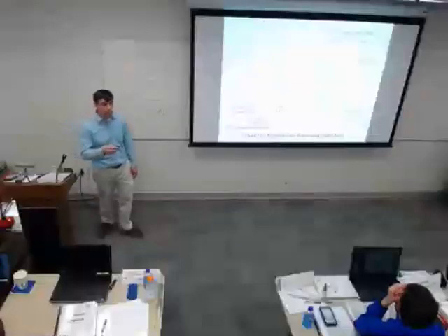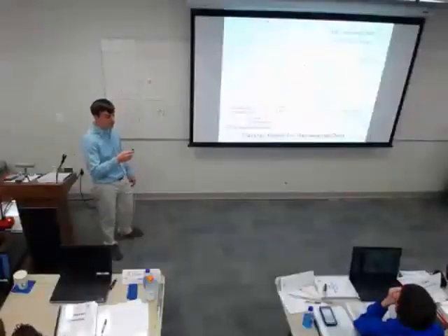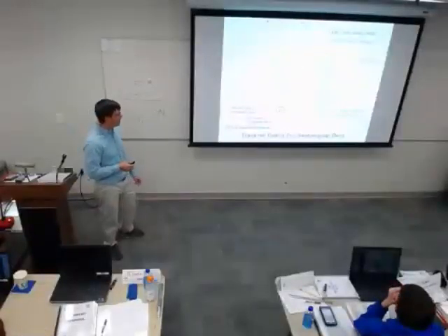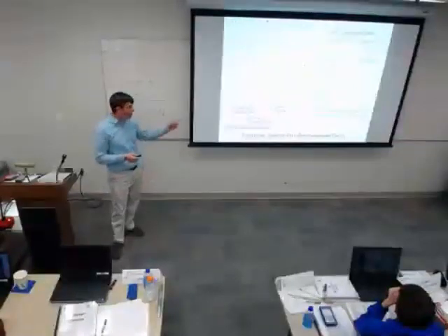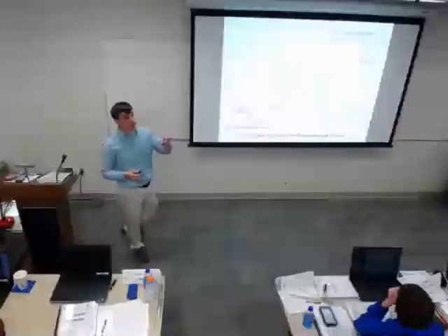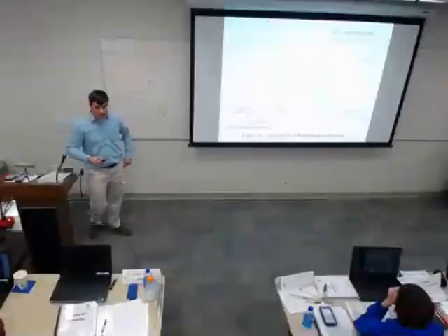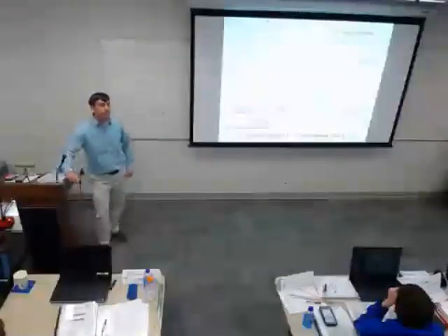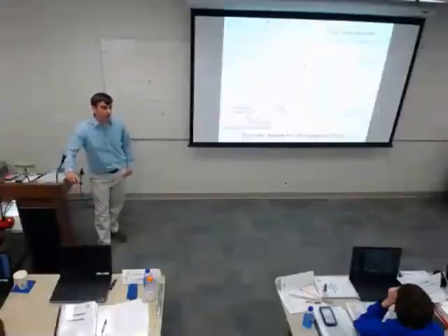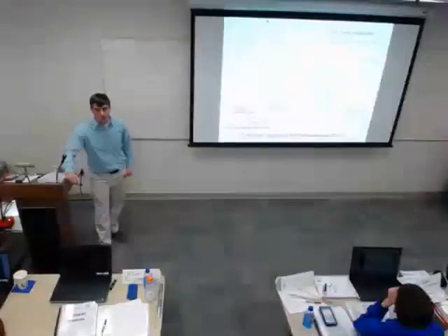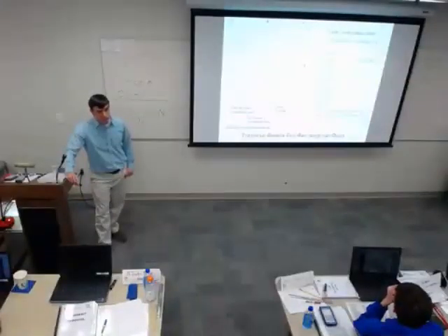And there is a requirement for the number of measurements needed and how they're supposed to be taken. Most TAB guys probably know it. I would have to go pull up the book to know how many holes he's supposed to have and how many measurements he's supposed to take. And be sure they give you the grid, because a lot of guys will try to just give you the average. I believe AABC now in their standard requires the grid, but watch for it. They didn't used to, and we got the averages, and you really need to see the velocity profile.